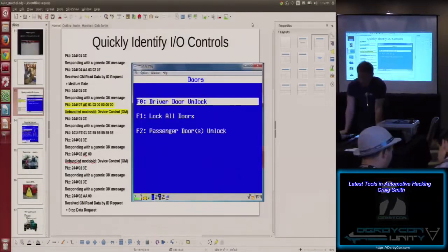The question is, do entertainment systems reside on the CAN bus? They do, most likely, if they come from your dealership. If you bought it third party, they usually don't. They're not always CAN either. For instance, I have a 2009 Honda, and that was on K-line, so it's a different type of bus. They are usually connected to your car, and getting into them isn't always through CAN. Sometimes you can spoof things to the infotainment.